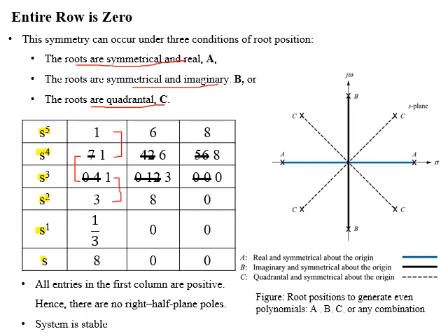So which means that now onward we will test for even polynomial. From third row to fourth row we have no sign change. From fourth row to fifth, and similarly from fifth to sixth we have no sign change.